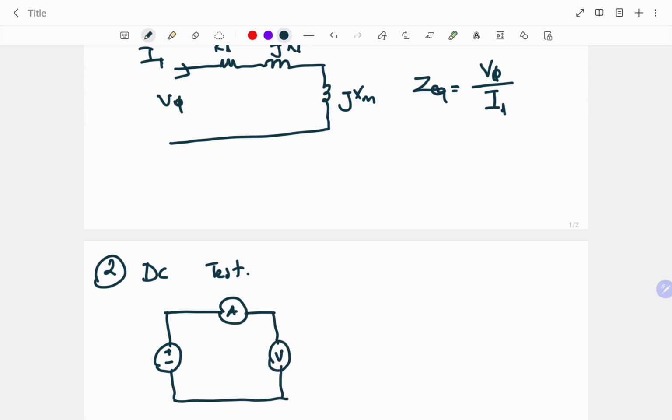For the source, we have a three-phase induction motor. Through the induction motor, the circuit will include only the stator winding resistance R1. All the other parameters can be neglected from the equivalent circuit because the system will not operate when we apply the DC voltage to the terminals.